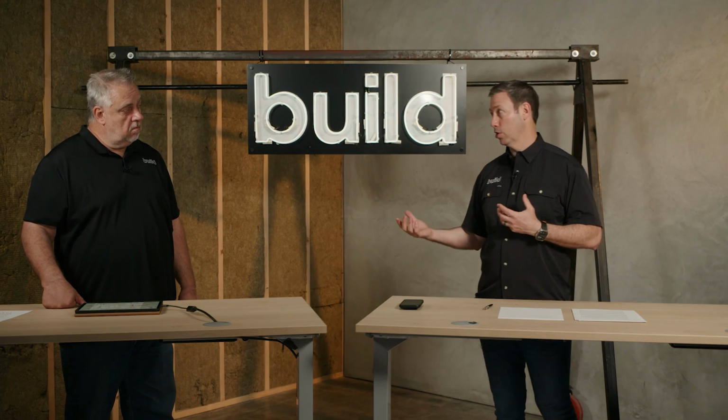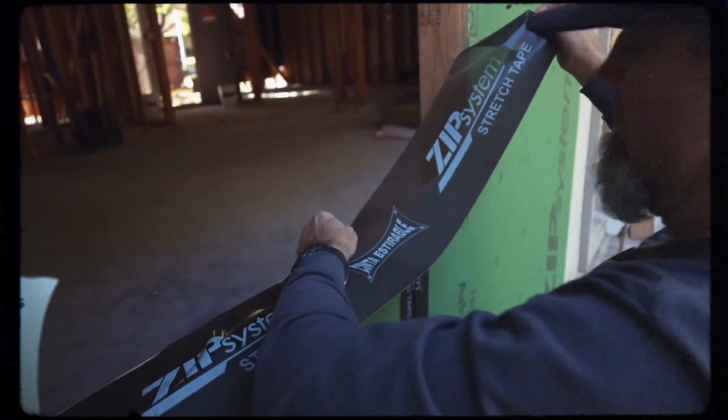And a water-managed install, where we give water a path to go. We assume water is going to get into that rough opening. The right question is, like David and Castro said, how do we let it out? So as a result, you'll see us, when we do our videos talking about all the different systems, no matter what it is, every WRB system has some type of sill pan that you can integrate with that.